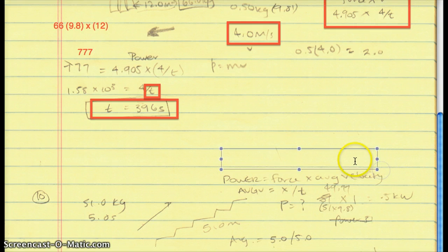So what we'll do is I'll actually write out our final, and we know that our force is always the 51 kilograms as is here, multiplied by 9.8, which is the acceleration due to gravity. Again, this is the mass versus force. We have our mass. We're trying to convert to force. So here we'll actually be multiplying by 9.8 to get our final force.